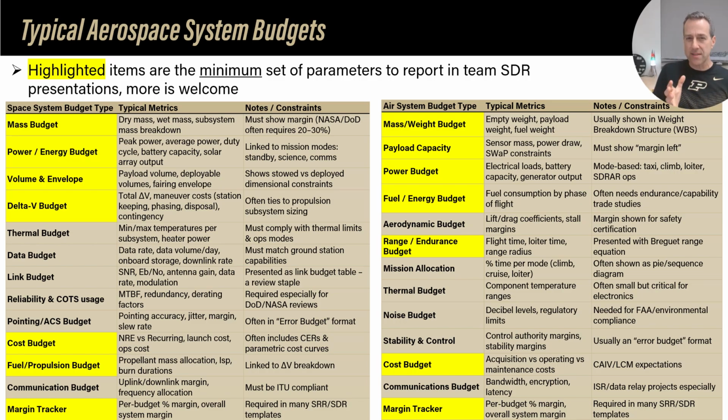But certainly in the early design phases, when things are pretty uncertain, there's a pretty hefty requirement of margin to make sure you're going to make those numbers by the end, especially if they're really tight. Like if you need to fit on a certain launch vehicle, and let's say NASA has procured a certain launch vehicle for your satellite, that means there's no flexibility to move to something else. So you have a mass you have to stay within, and they're going to require a pretty big margin, especially at SDR, the very earliest design review.